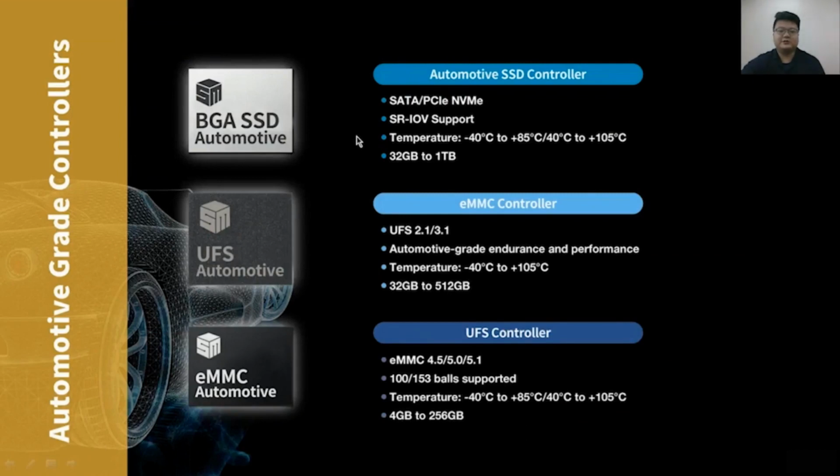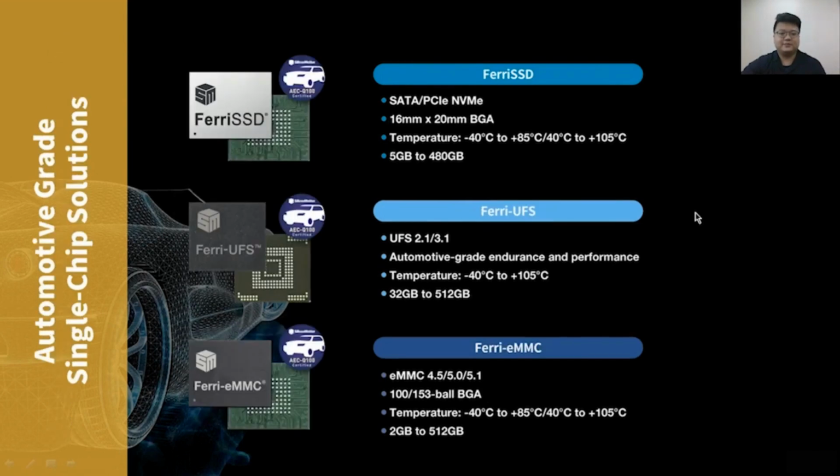For automotive grade controllers, SMI offers SSD controllers, eMMC, and also UFS for each application and feature. And we also have SR-IOV support on our PCIe controller. And all the controllers pass AEC-Q100 Grade 2 and Grade 3. For the automotive grade single chip solution, we also offer BGA SSD, UFS, and eMMC. Each of them also passes AEC-Q100 certification for Grade 2 and Grade 3.